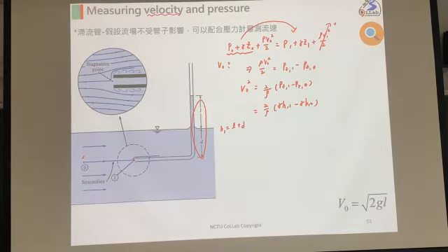And what is head 0? Head 0 is here. So you see the water depth only has D, right? We only have the water depth D. So head 0 is D. Okay, so we put the head values into the equation. Here is 2, and I move the gamma outside.